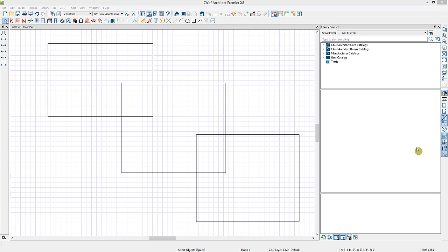As I mentioned before, some of these tools over on the right side of my screen are toggle tools for preference settings. Some of them, however, are toggle tools for default settings. Defaults are saved in the individual plan, not globally in the program. For instance, the blue grid that you see on my screen. This grid shows us 12-inch by 12-inch boxes.